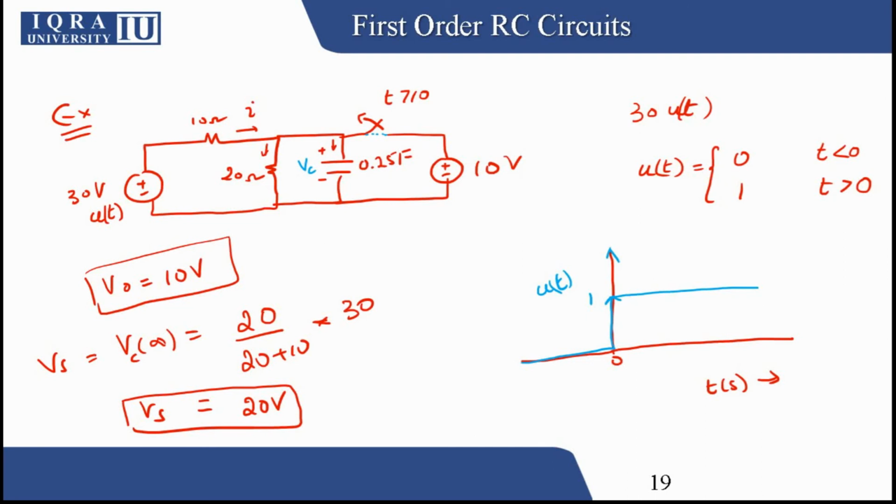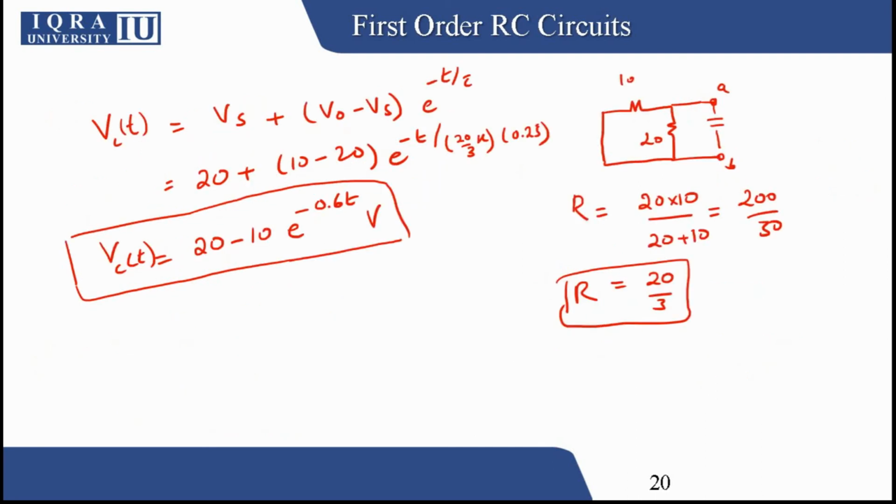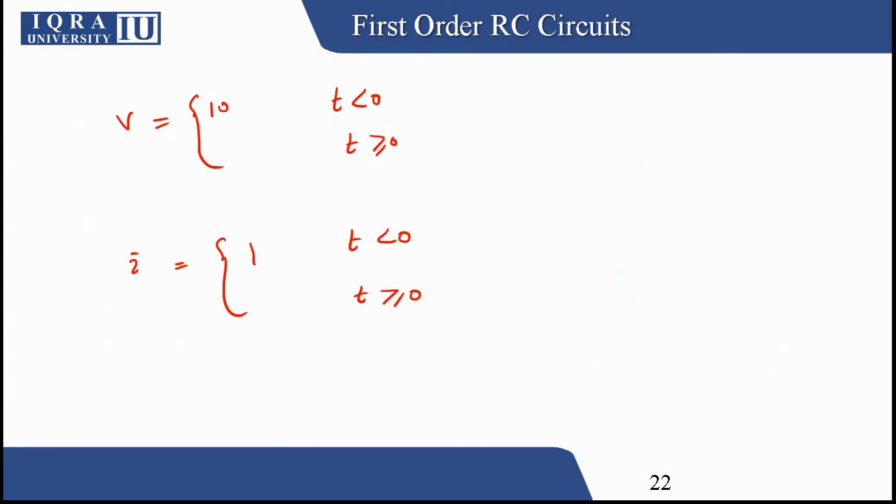It will be, because this voltage source is 0 and this is a short circuit, the voltage across the node is 10 volts. So 10 volts divided by 10 ohms is 1 ampere. So we have 1 ampere current. Making it a simplification of all the resistance, if this is 10 volts, the complete node will have 10 volts.